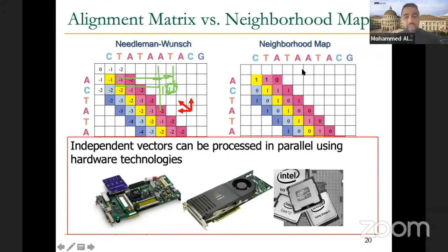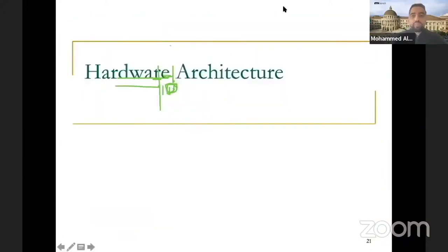However, in the GateKeeper, you can have every cell replicated, or the module to calculate a single cell or multiple cells can be replicated to parallelize inside the problem of solving 2 sequences. So you can have the parallelism at the level of sequences as well as at the level of the entries of the DP matrix. And this is where we got the 130x speed up, for example.